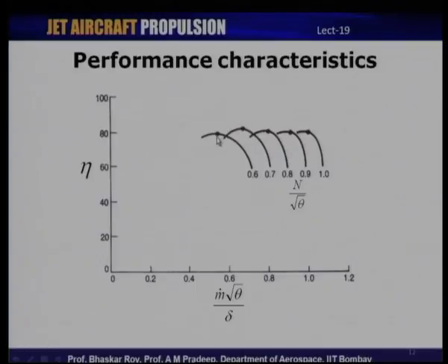So, we see that even in the case of efficiency, as we approach higher speeds, the efficiency characteristics also attain a drastic droop, which means that the band of high efficiency drastically drops as the compressor is operating at higher speeds and as it approaches choke, whereas for lower speeds we have a relatively larger band of high efficiency operation.